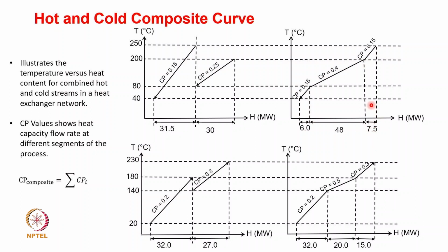How are you getting these numbers? Simply by plotting it. So there is no way to analyze further. Once you plot and integrate them together, at the points where they intersect, you drop a perpendicular down and find out what the coordinates are, and thereby compute the individual heat utilities of these particular streams. In fact, it's not a heat utility, it is the delta H values.